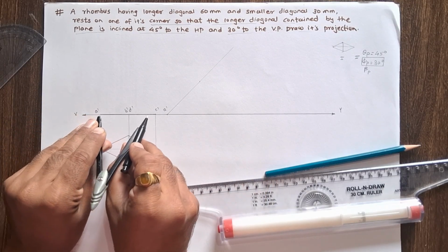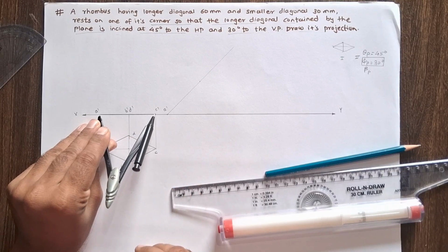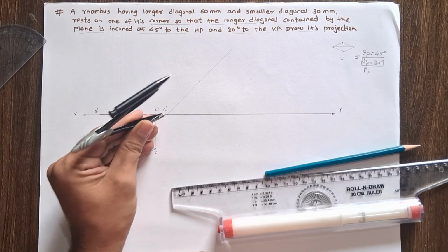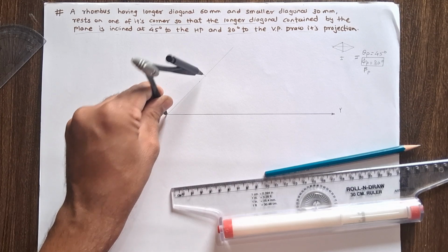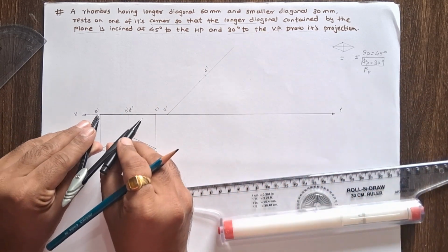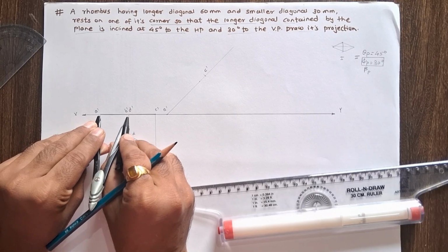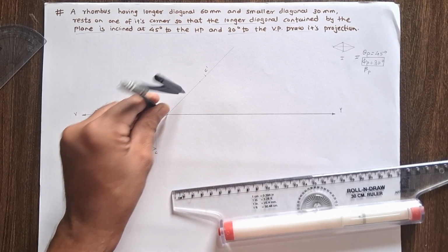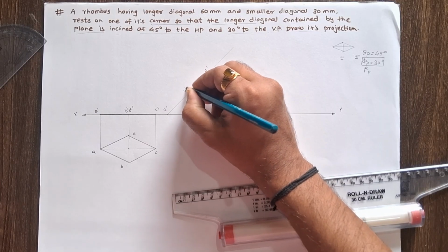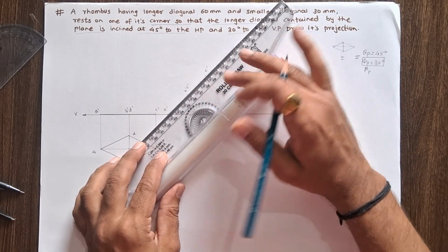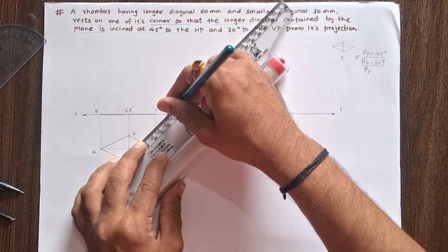For that, measure the A dash C dash distance in the compass. This is the stage 1 front view. Place the compass point on A dash and mark an arc on this 45 degree angle line. So here we get the C dash point. Now measure the a dash b dash distance, and from a dash mark b dash and d dash. Now join a dash and c dash by using a thick line. So this is the